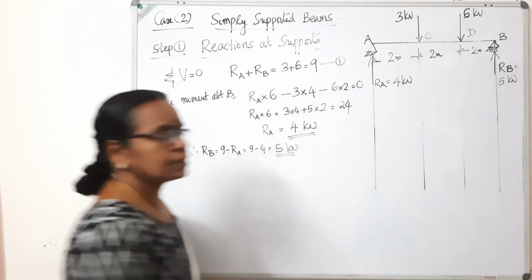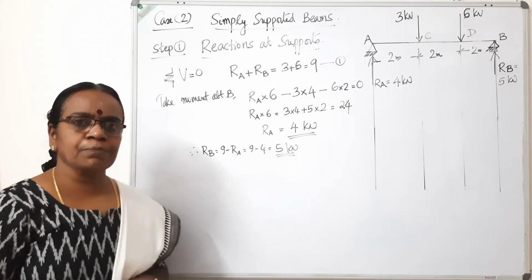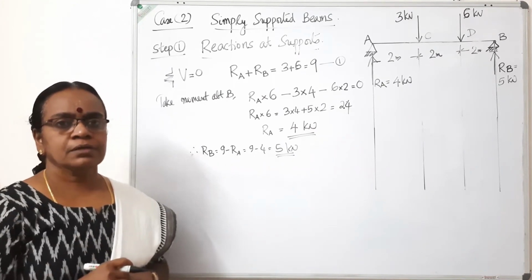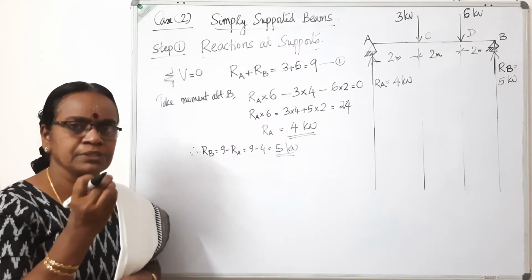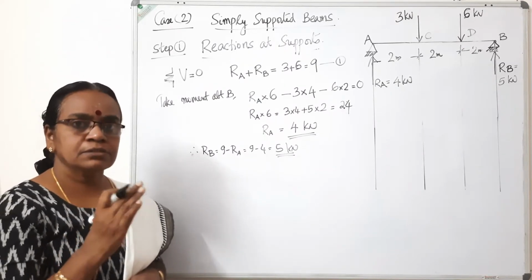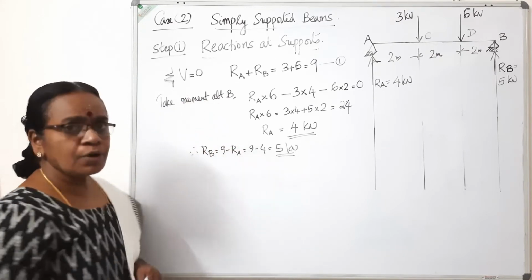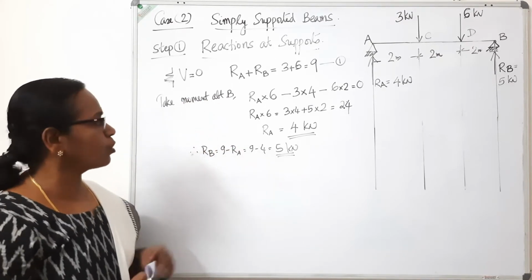So that is the first step. You have to compute the support reactions correctly. Only then the remaining portions will be correct. So spend some time, double check it so that the support reactions are correct. That is the first step. Now, the second step is as usual. We have got all the forces now.